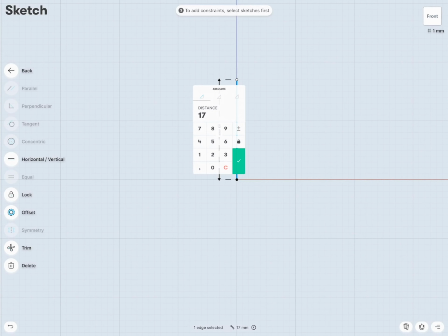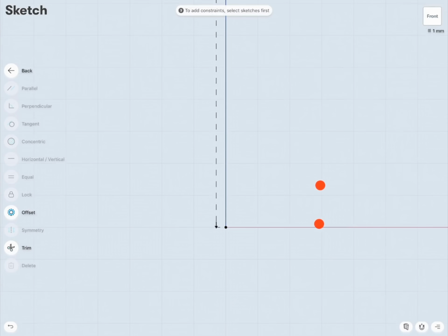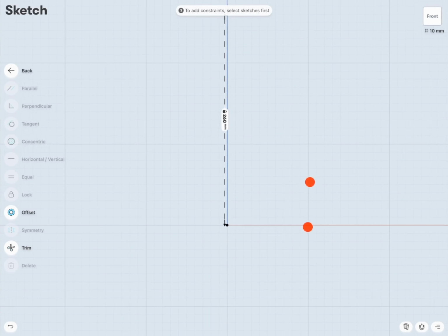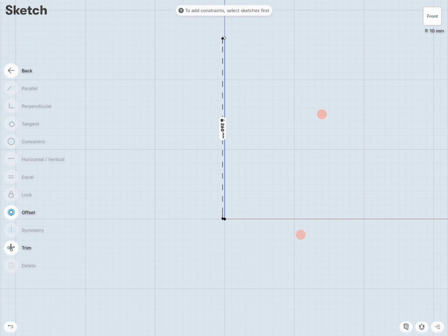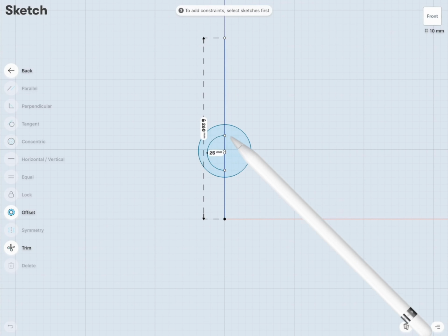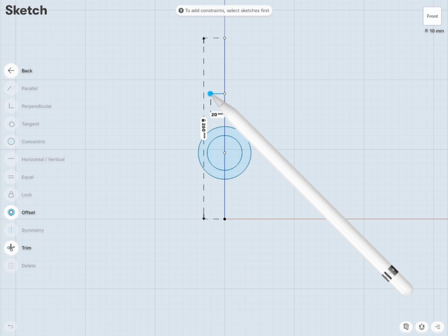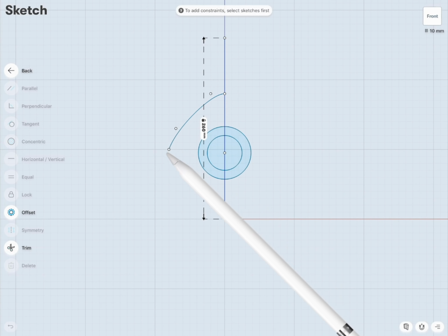You probably noticed that I'm locking one point of the plane. I'm doing it in order to keep my endpoints in the same spot and resize the sketches according to that point. Now let's create the profiles. I will sketch them as circles, and then I will align them by selecting concentric alignment in the sketch menu. Now I will create the spline for the profile.